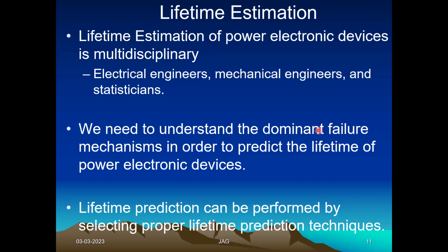The mechanical engineer should tell, if you turn on like this, turn off like this, with this much voltage, this much current, this much heat will be generated. And if you use this particular heat sink with this particular blade or the motor, the method is called forced air cooling. Using a fan, you force the air towards the hot body so that it gets cooled down. That is called forced air cooling.